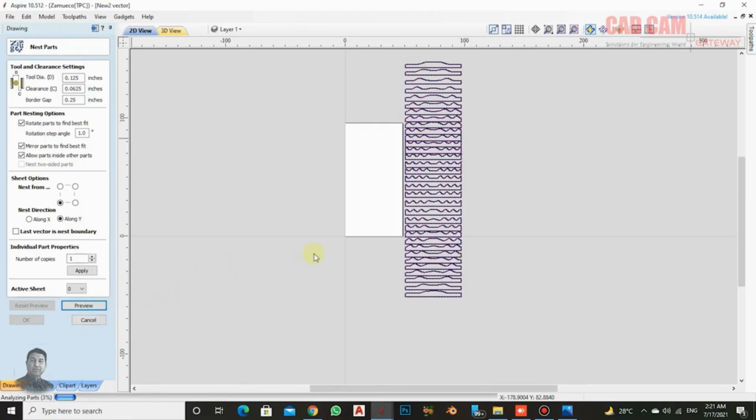But when you're working on nesting, there's one thing you should definitely keep in mind. All the components need to be selected separately. Look at this. When you come to nesting, there's one thing you absolutely need to keep in mind. All the components should be selected separately. See, it has selected all the components individually, and each one has its own boundary. This step is very important.